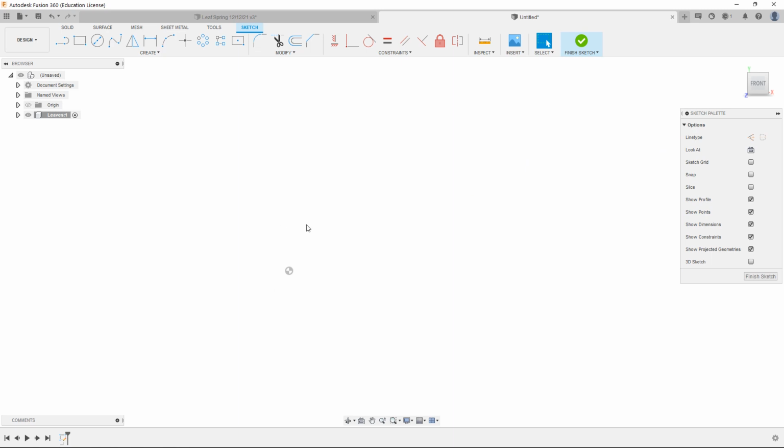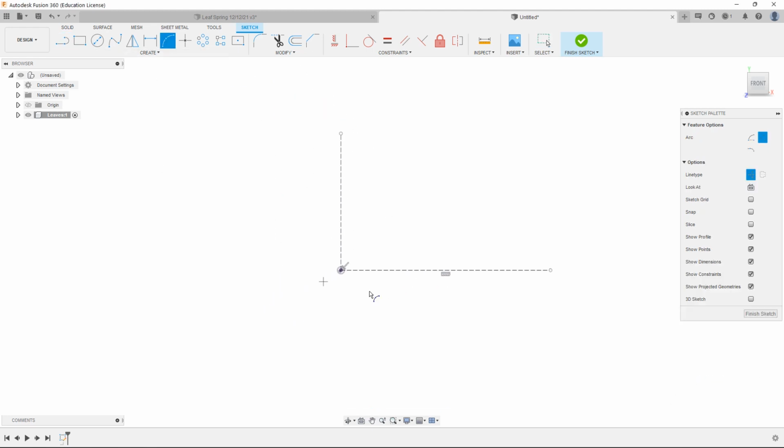Now we need construction lines so that we can use them as a reference to whatever we need to draw more. So toggle this construction and select line, and we need a horizontal and we need a vertical. Great. Now that they're ready, let's get into drawing.